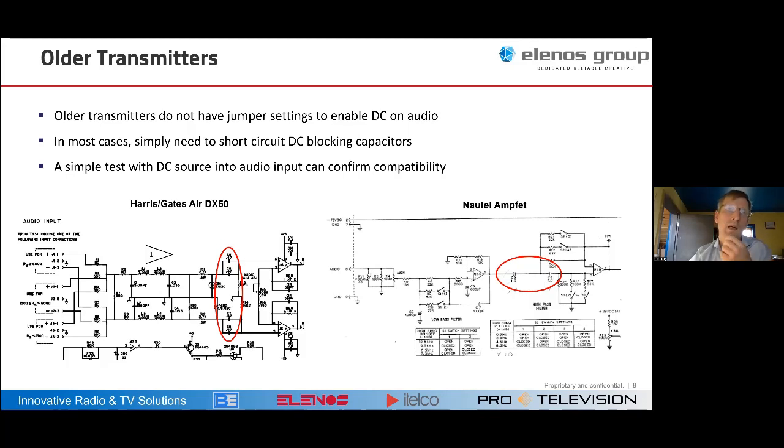All right. But basically, there are some tube transmitters that are, I believe the correct term is, I hesitate to use the term because I'm not sure everybody agrees on what it means, but plate modulated, to me, essentially means that the power supply to the final stage carries the whole envelope, the DC of the carrier plus the audio. So any tube transmitter that works that way would be compatible. All right.